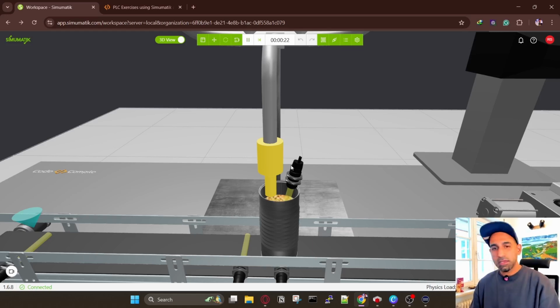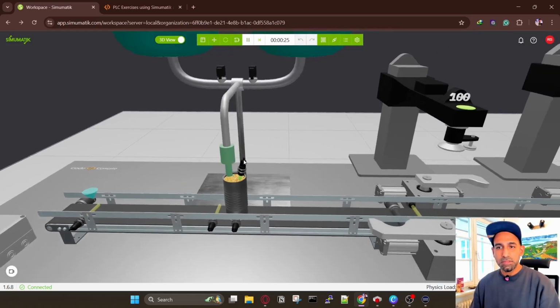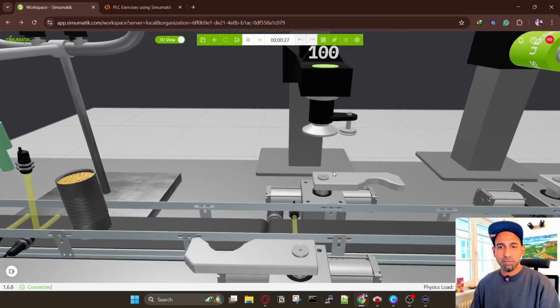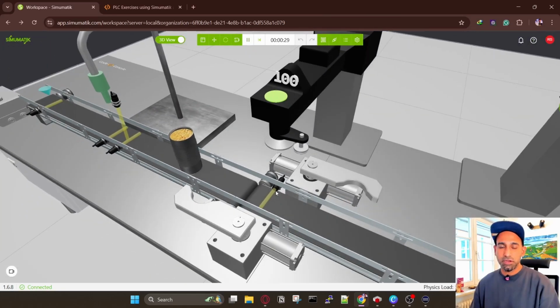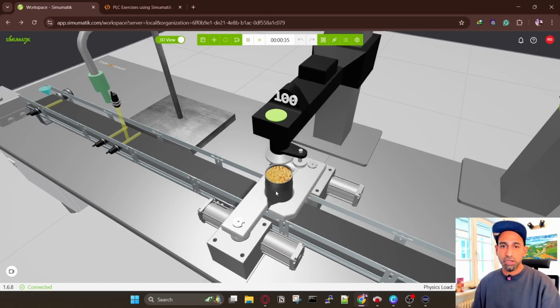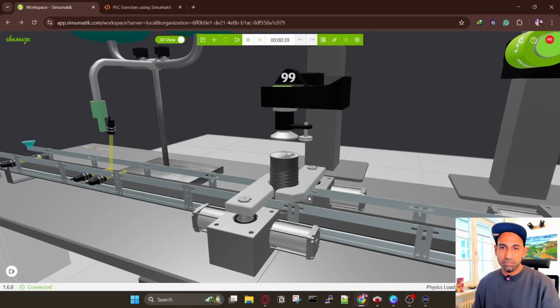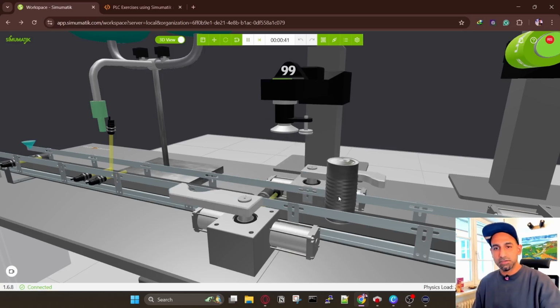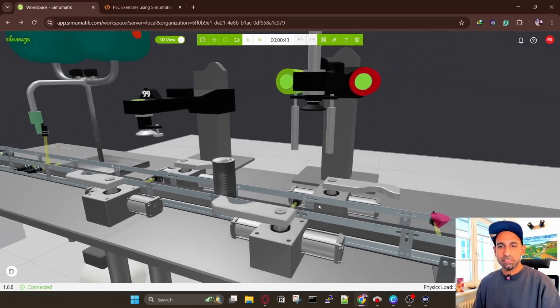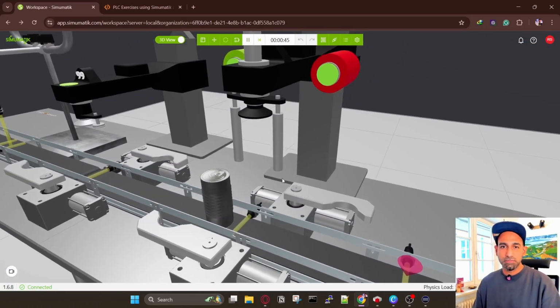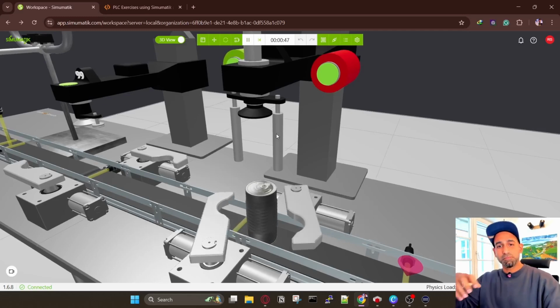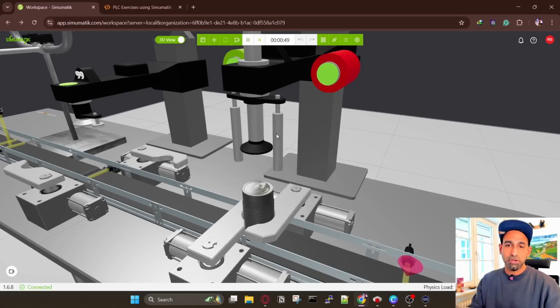The next one is the unit for sealing. There is a sensor here. It will detect the can, and these jaws will close, and the jaws also have a sensor inside, which I will show you shortly. Then it will come down, rotate, turn, and seal it. Once it's sealed, it will be removed from this unit and go to the next unit, where another unit will pick this workpiece up, you will see shortly.